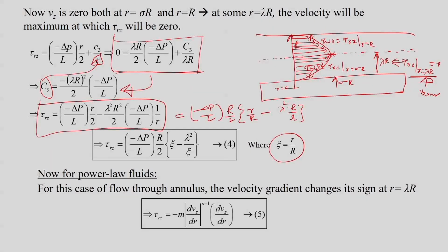So, we can clearly see the shear stress distribution between the annulus of two concentric cylindrical pipes is very different from the shear stress through one single cylindrical pipe. Okay. So, for two different geometries, though the geometry is cylindrical, the shear stress is very different. So, obviously velocities also would be different, because here the flow is taking place in the annular region, not inside the pipe.